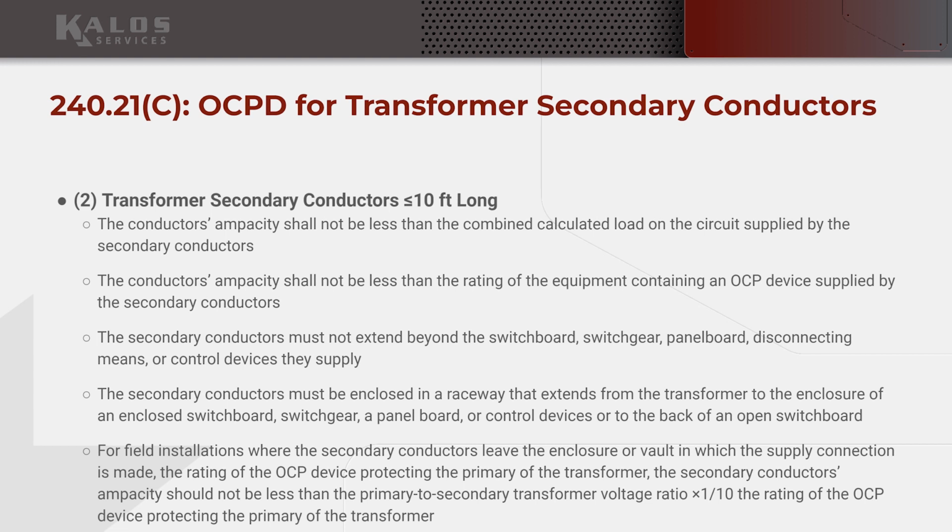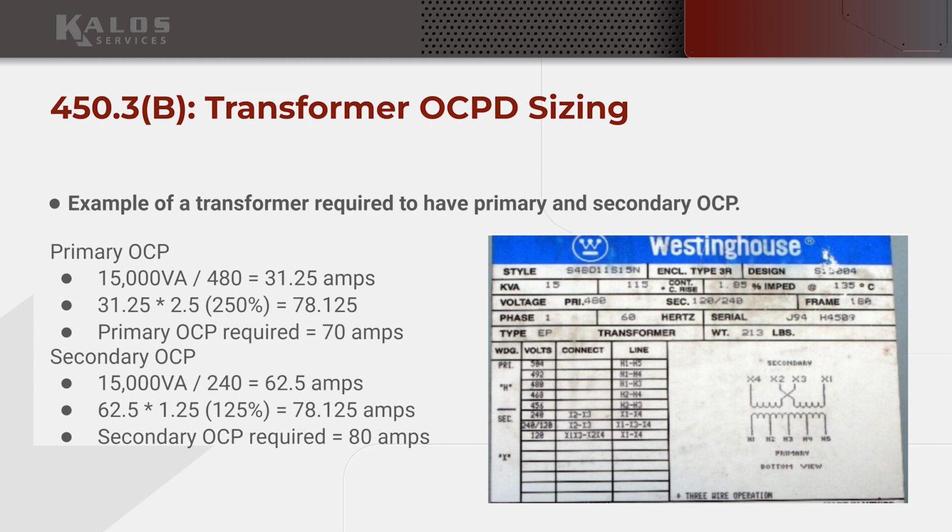Just size it to the size of your overcurrent protection, which you've determined by this math here. So 80 amps, I believe that to be 4-gauge wire. You're going to be fine with 4-gauge wire in a 10-foot tap rule and following a 10-foot tap rule.